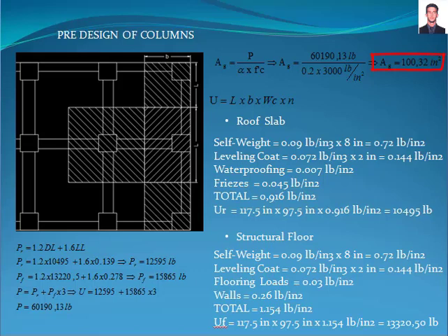The American Concrete Institute 318, Section 18.7.2.1, defines for a special moment frame system the dimension limits for columns, and establishes that the shortest cross-section dimension of a column should be at least 12 inches, which means the minimum gross area for a column is 144 square inches. Our column doesn't meet this requirement. The gross section for our column will be 144 square inches.